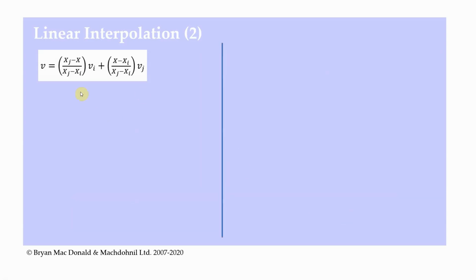From our previous slide, we essentially had this equation here. We can notice that it is of this form, which says that the vertical displacement of any point is Si vi plus Sj vj. The functions Si and Sj are known as the interpolation functions or shape functions.